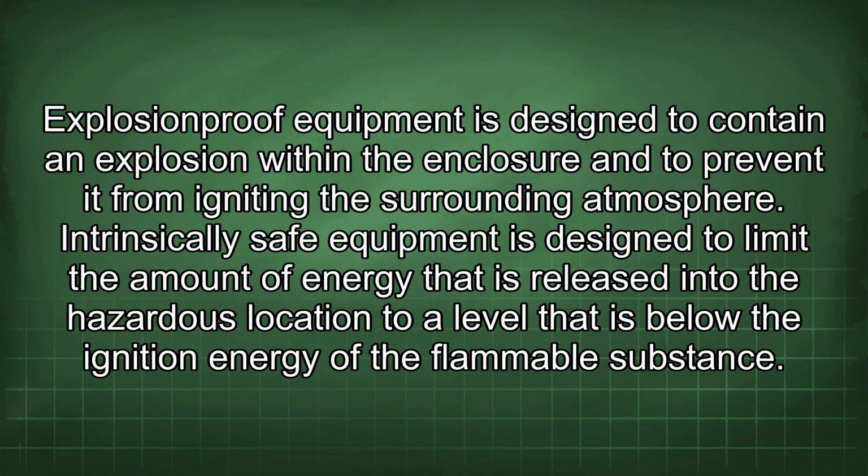Explosion-proof equipment is designed to contain an explosion within the enclosure and to prevent it from igniting the surrounding atmosphere. Intrinsically safe equipment is designed to limit the amount of energy that is released into the hazardous location to a level that is below the ignition energy of the flammable substance.